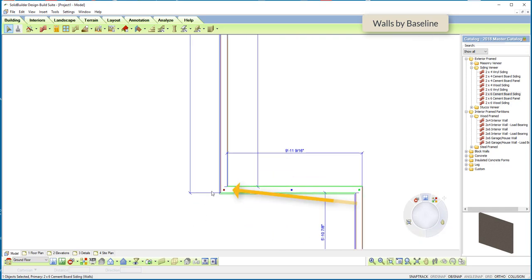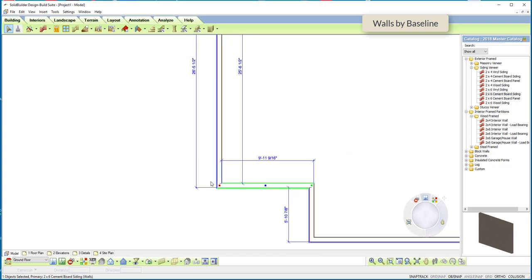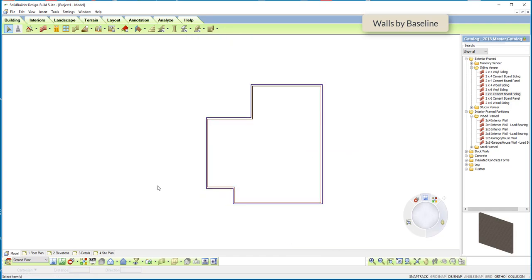And you'll see this red dot. Everything in Solid Builder feeds off that center line, so that allows you to flip openings, flip doors, and adjust swings. That's just the way it works, even with overhangs. So many times as a user, you would like to draw this layout and use your distance entering so that you get the 26 feet, not the 5.5.